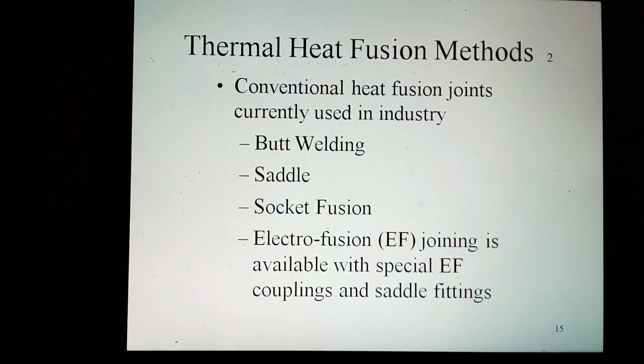Thermal heat fusion methods. There are 3 types of conventional heat fusion joints currently used in the industry. These are butt welding, saddle, and socket fusion. Additionally, electrofusion joining is available with special couplings and saddle fittings.